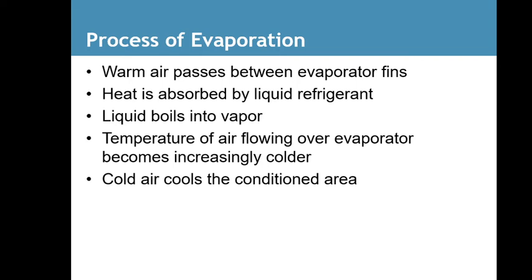Liquid boils into a vapor. Again, this is a place where it's 410A. It boils at about 53 degrees. The temperature of air flowing over the evaporator becomes increasingly colder. Cold air cools and conditions the area.